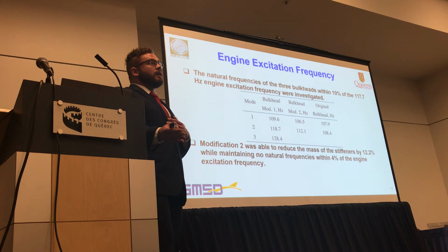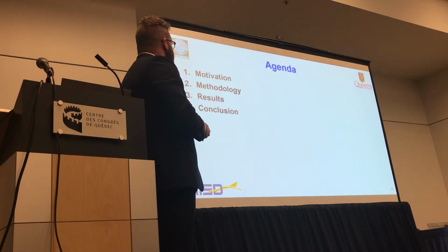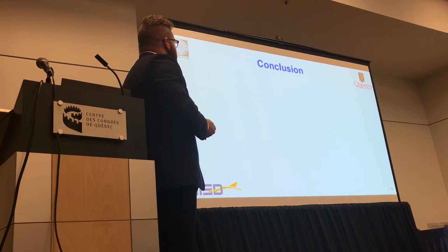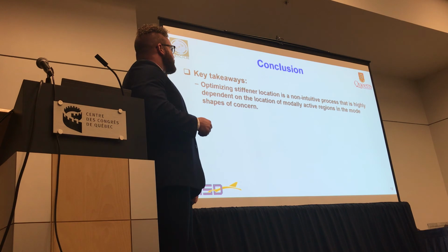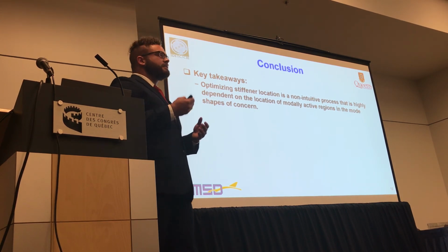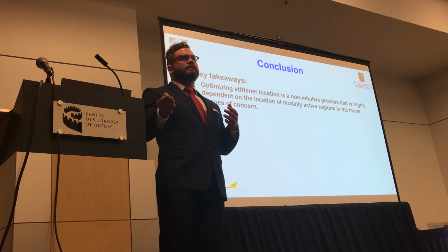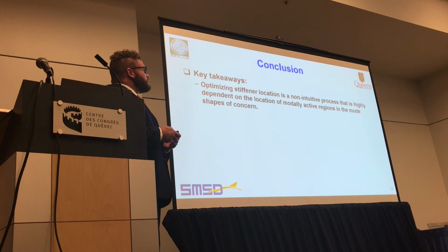For the intents of this investigation, I consider this to be the optimal design. However, I have not performed any structural considerations, so that would obviously need to be taken into account. So in conclusion, the key point that I want to take away from this investigation is that optimizing stiffener location is a non-intuitive process that's highly dependent on the location of the modally active regions of the bulkhead.